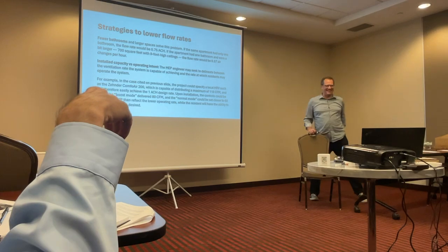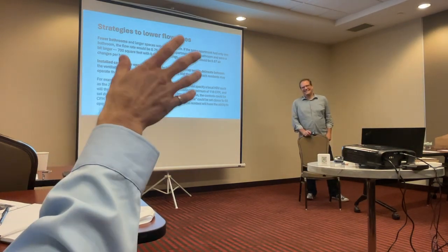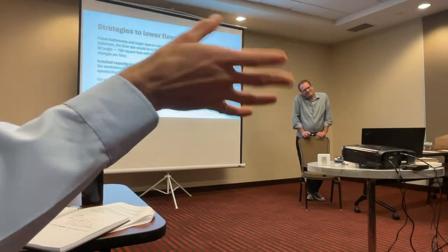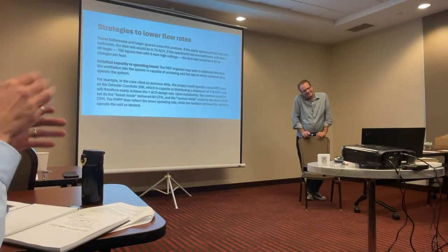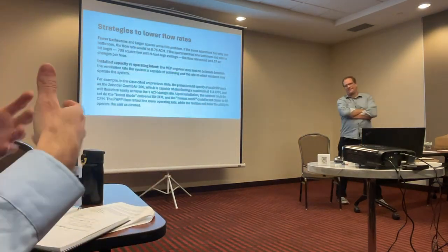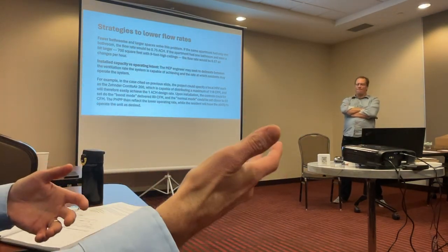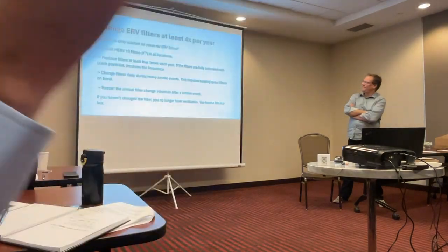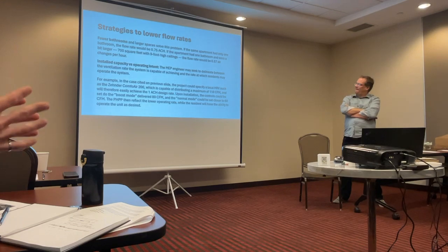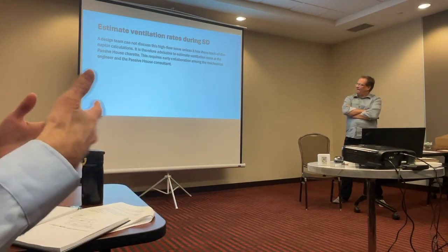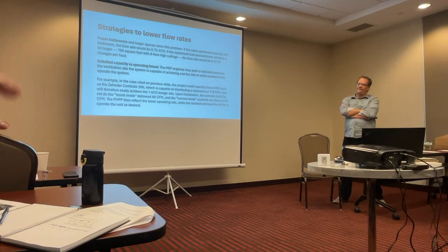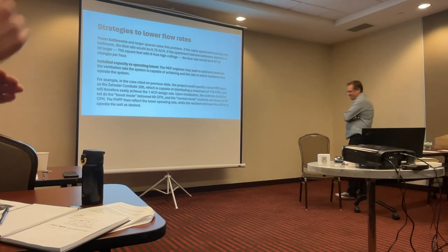That's what I would stress, which works in most jurisdictions, this new ASHRAE revision aside: you design to your local building code for sizing, but you run it at your Passive House rates and you commission it that way. Most building inspectors aren't going to appreciate the difference when you come to commissioning. Then make sure your Passive House consultant understands what rates you should set, and make an agreement with the engineer. That may end up somewhere between Passive House and code, which they may be comfortable with, but at least you're partway there.